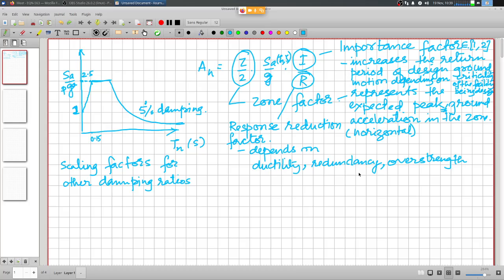And you happily use that reinforcing bar as 415 MPa, and the actual yield strength might be much higher than 415, who knows. So that is the overstrength. You might actually provide much greater steel strength capacity than what is required. So is that a good thing?